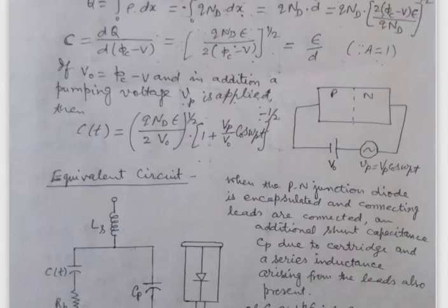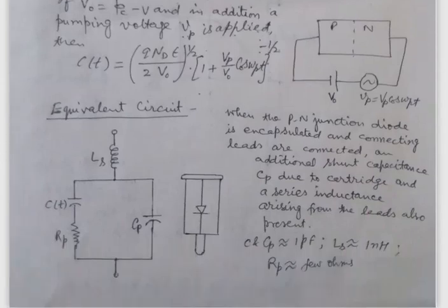Therefore both these two diodes, the linearly graded junction diode and the abrupt junction diode, will be used as time varying non-linear capacitance, that is, as Varactor diodes, and these will be used for the amplification of the microwave signals.